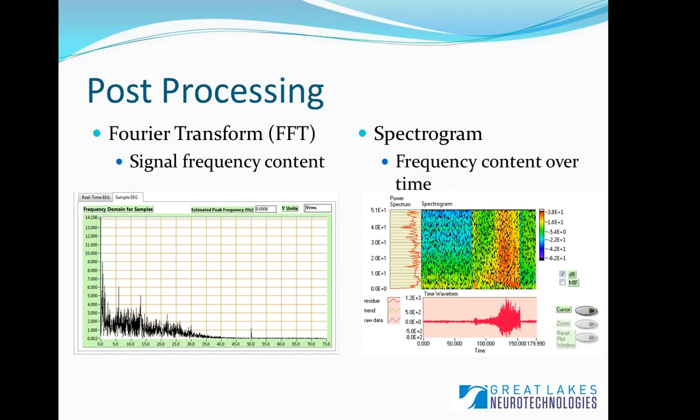From this plot, we can see that as time progresses, the frequency content goes from typically very low, and we start to see an increase in higher frequency content of the signal. This may be, in the case of measuring EEG over premotor or motor cortex, may indicate somebody is planning or initiating a movement of their hand or whatever. And so you could combine this type of analysis with other biomedical signal inputs to start to understand how the system is working.